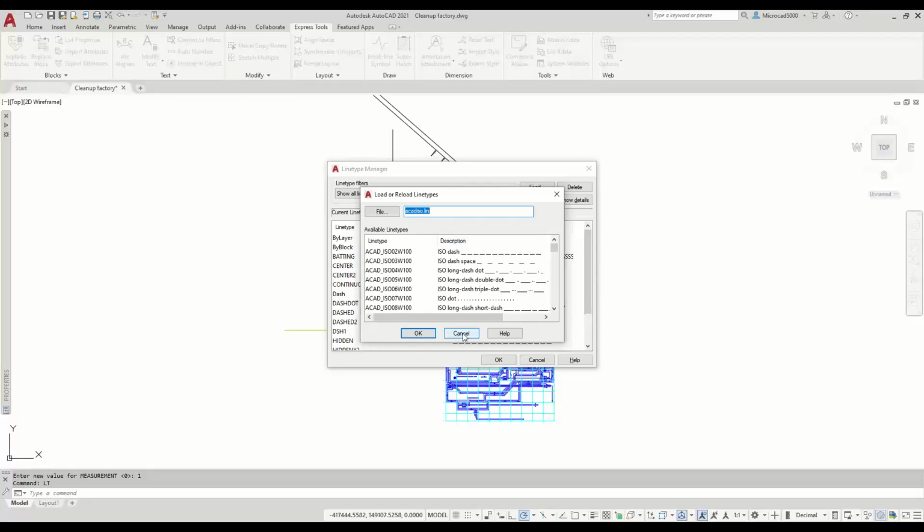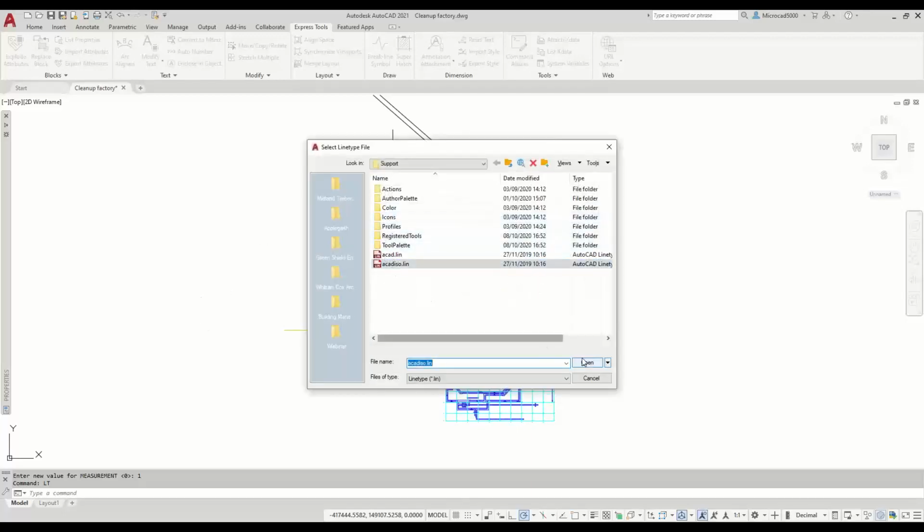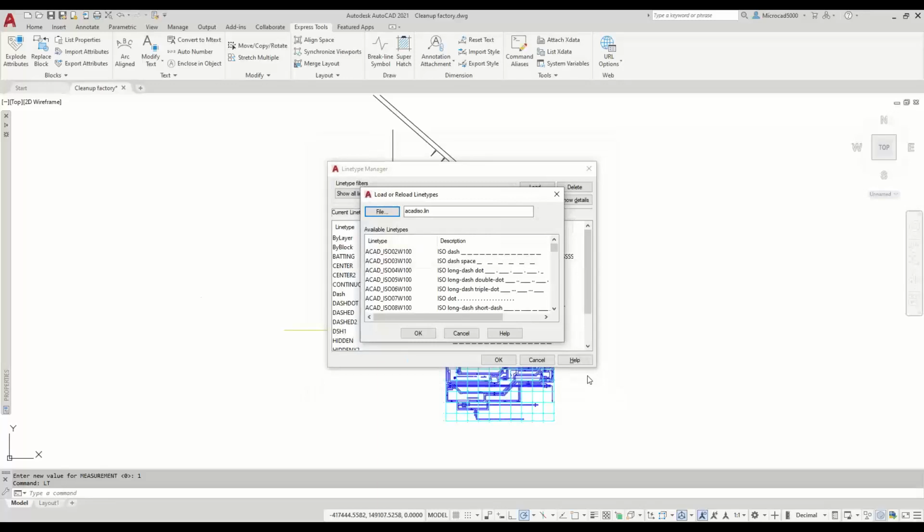Now, with line types, yes, you can select an imperial definition file or a metric one just by overriding it there. However, if you have that measurement set incorrectly, i.e. 0 for imperial, your drawing will use the imperial hatch patterns. So I can hear people already saying, oh yeah, that's why my hatch pattern didn't show correctly. You'll try to hatch and suddenly it'll obliterate the screen with a million lines because you're using the imperial hatch pattern. So make sure measurement is set to 1.